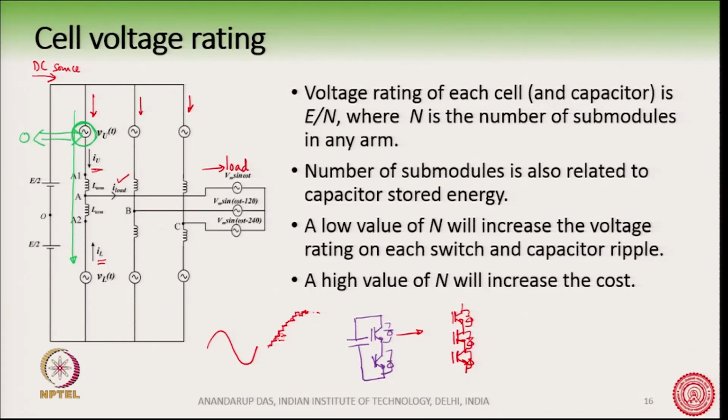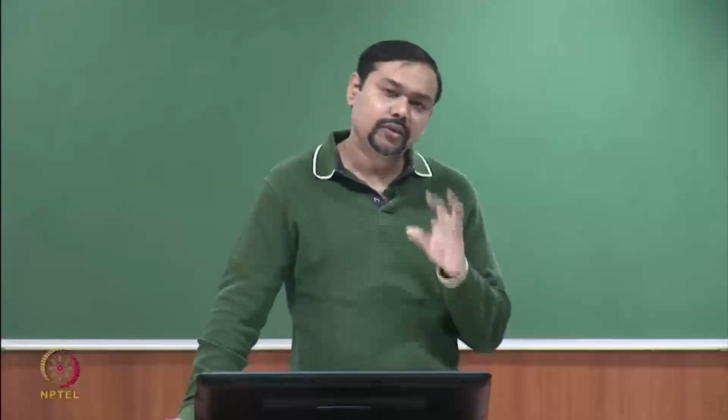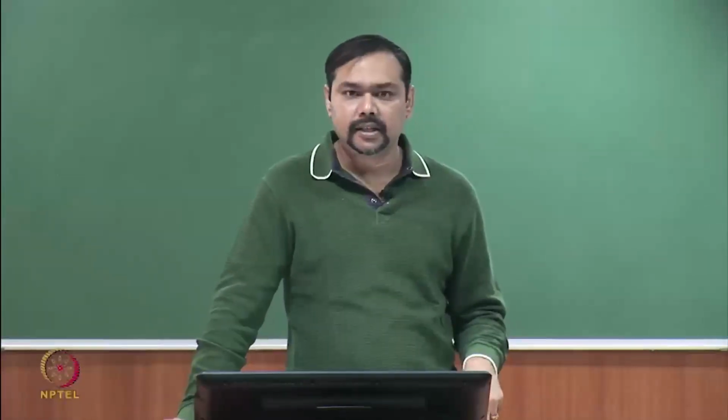Without the circulating current, the voltage on the arm will go wayward. It will go very high or very low, either to the DC bus or to 0. Because the real power is flowing through the arms, the arm is losing or gaining energy, and we do not have a mechanism to compensate.